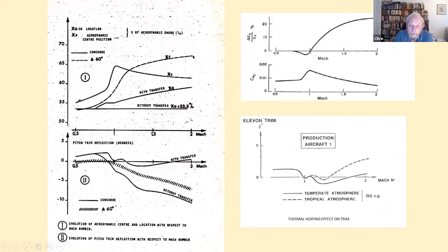And that is a big shift of aerodynamic center you have to contend with. With our camber changes, we were able to change that so that the aerodynamic center sort of peaks at about Mach 1, but comes forward to about 62% or something at Mach 2.